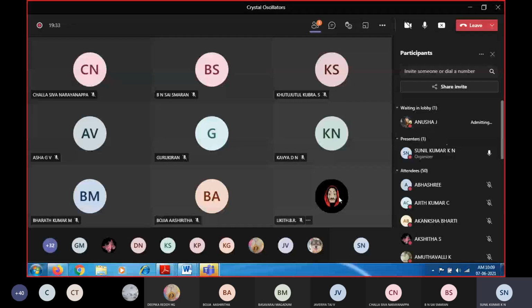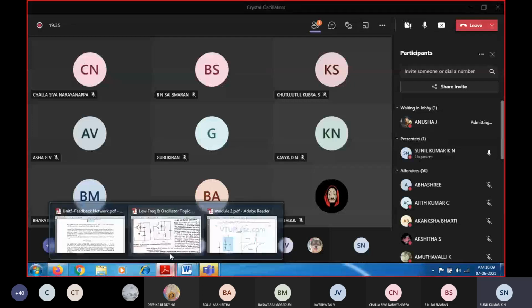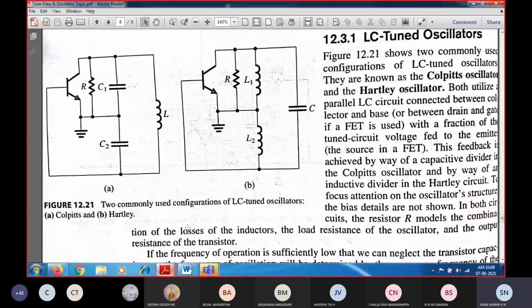Before that, we will just see the LC oscillator as well. In that, we have seen the Colpitts oscillator in detail. We know that the amplifier in the main network comprises a transistor, and in the feedback network an LC tank circuit is there. The inductor and capacitor, being energy storage devices, are considered a tank circuit whenever connected in the feedback path.